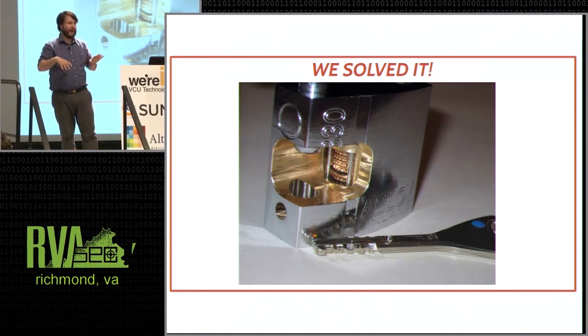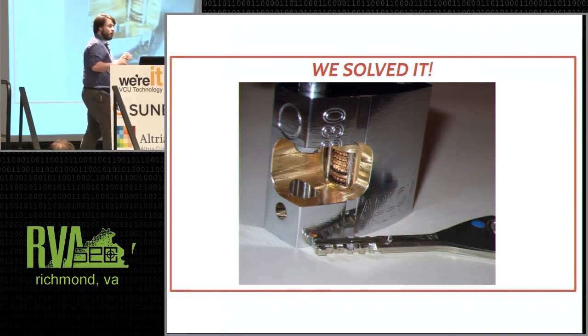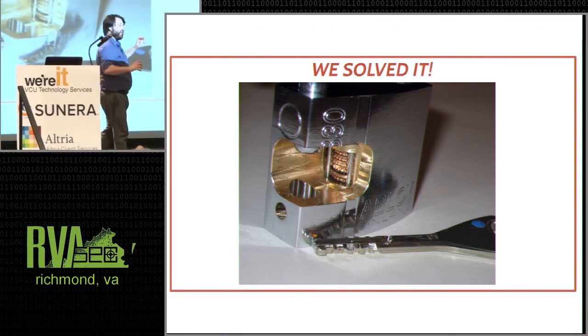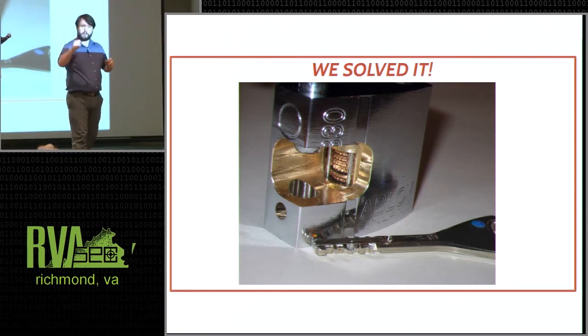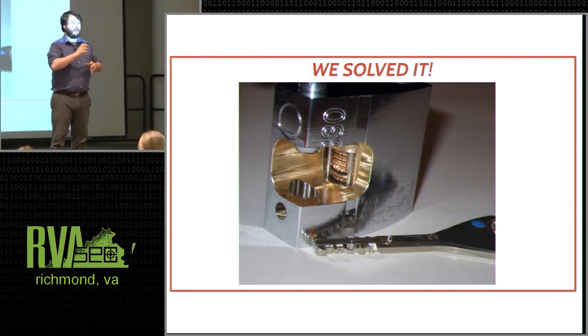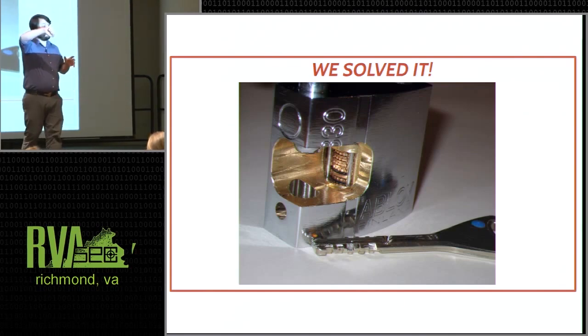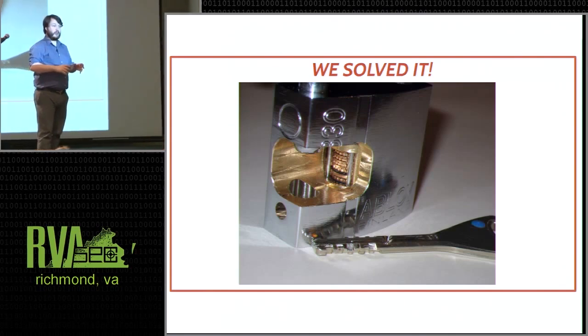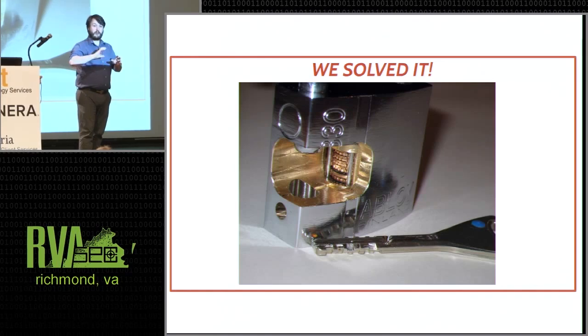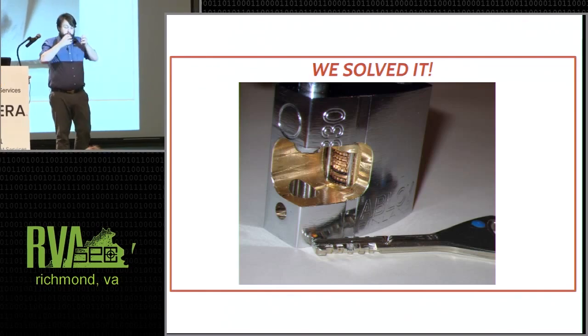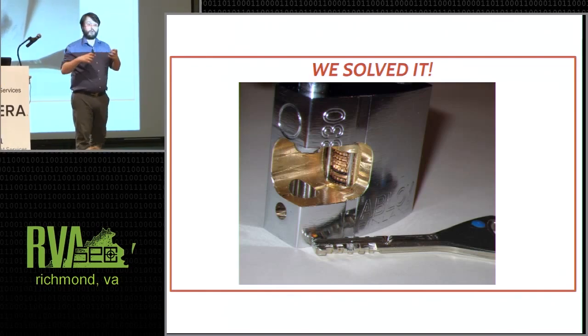Anyway, how they solved this was that they separated the act of applying pressure from the act of manipulating the individual tumblers. So, the moment that you apply pressure to the tumblers, you cease being able to turn them. So you can turn them and then try, and turn them and then try. You could build some tiny machine to potentially brute force this, but you can't feel how the tumblers interact with their sidebar.